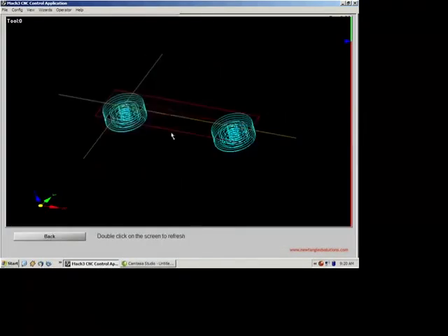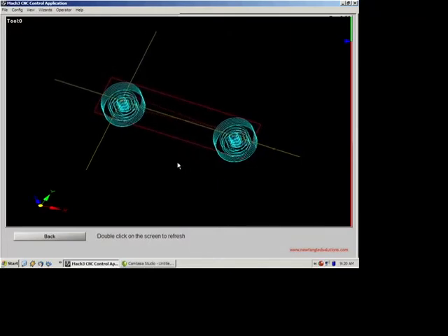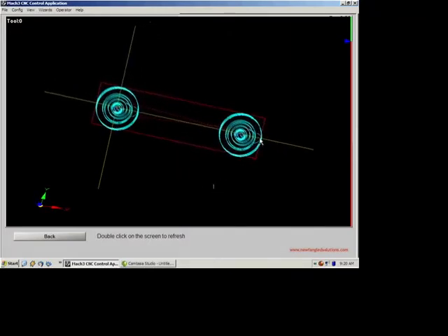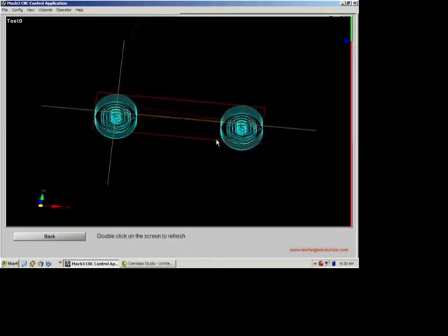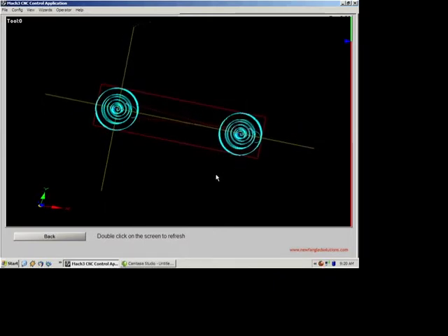We'll verify the toolpath. So now we have 2 pockets and 2 finished passes. You may look at this and say, wow, that's an awful lot of material that we're going to take away. This is actually the new compensation that's done inside of Mach3, the advanced comp. There's a G-code that is set in the beginning that actually sets your machine to advanced comp whenever you run one of the newfangled wizards. We did this because it's a little bit better compensation routine, and it gives you the opportunity to have a pocket that you can actually tweak the size of without reposting the program by adjusting a P parameter.